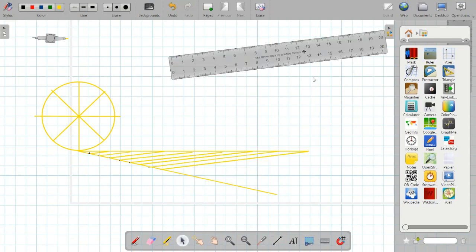Now, once this is done, we will start naming the points. Again, an important part: if you do the naming wrong, the entire involute or cycloid may come out wrong. So let us start with the point which is given in the question. It is given that you have to trace the locus of point P on the circumference of the circle. But where point P is, is not mentioned in the question. So we can assume it wherever we want on the circumference of the circle.